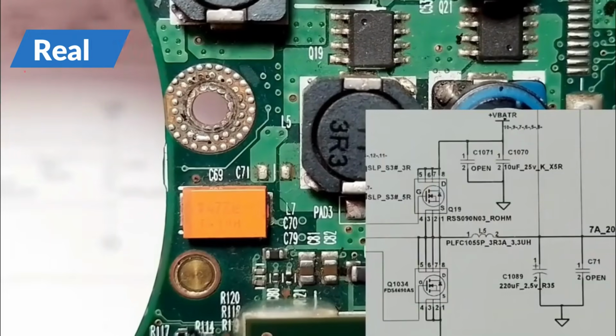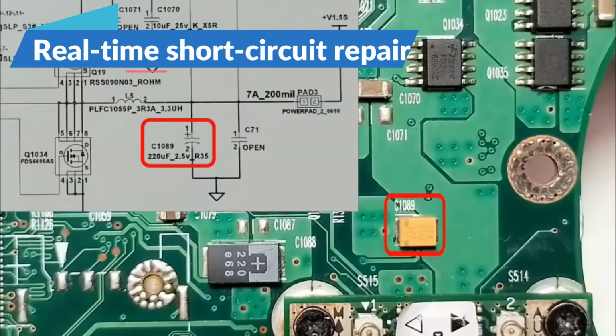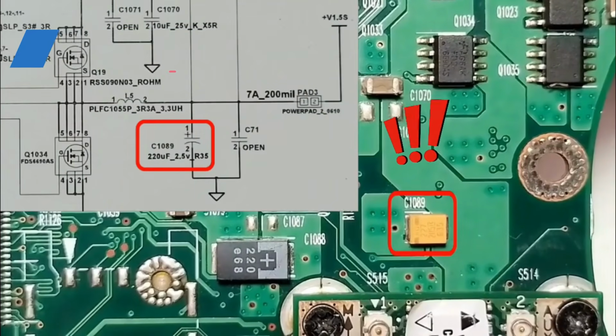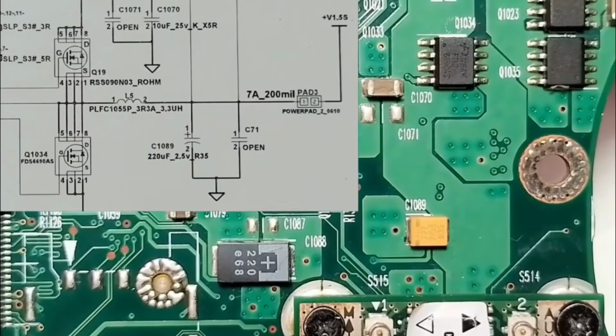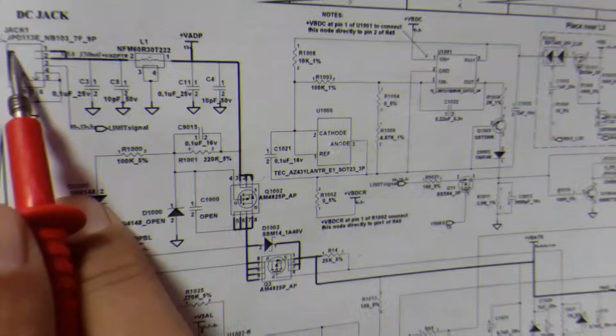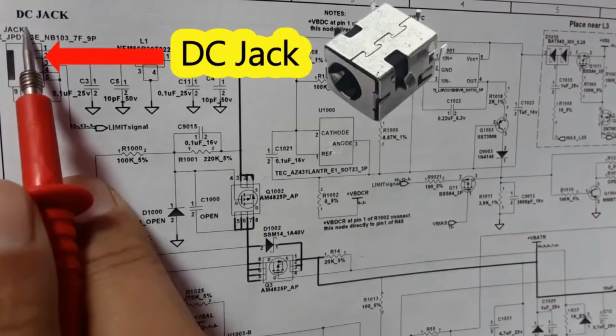We have C71, it's not connected. Here we have C1089. This could be the failed or the shorted component. And we have here Q1034, the MOSFET. Here we have the DC jack, as you can see.